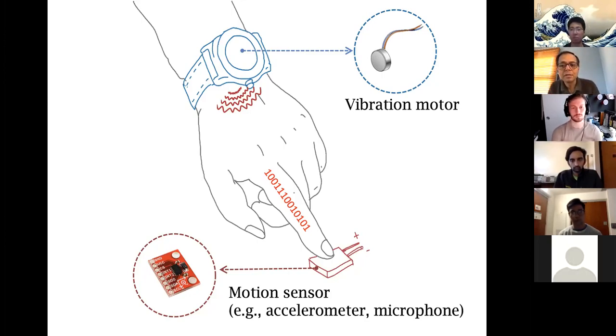What should you see? In those 5 FFT bins, you should see the first bin having higher amplitude, with some noise of course, the second bin lower, the third bin lower, the fourth bin higher, the fifth bin higher. Of course, there's noise. If the noise is large, you might think the low amplitude is actually a high amplitude, so you might have errors. But if you're just saying 1 or 0, you can make the high amplitude much higher and the low amplitude much lower, and hopefully you will get that same effect at the accelerometer.